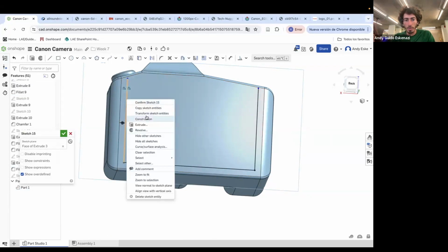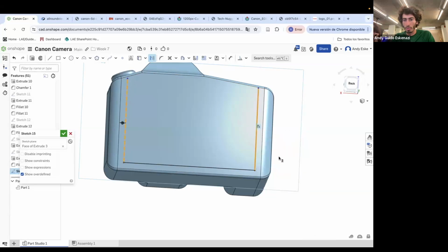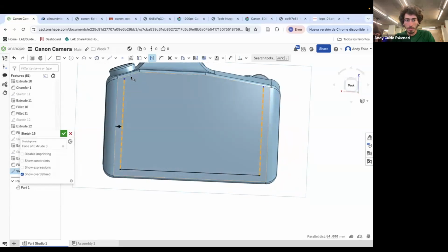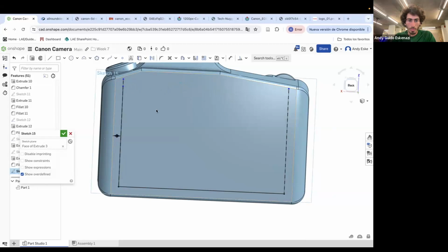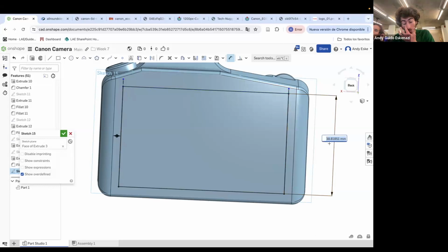That's fine. We can say by 3. But all of these lines, at least these two, I will make them construction like that. Very good. And now to dimension this, I think if I were to go to my friend the hashtag and I go to height, I'm gonna do again our little trick of 0.8 times height. So I think that's gonna work.